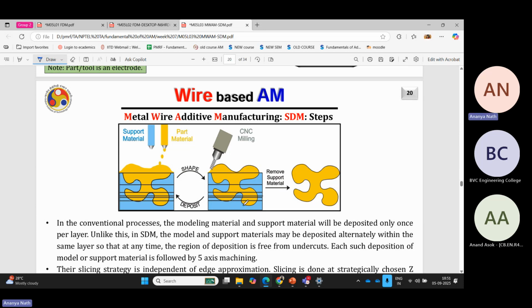So this is the shape manufacturing process where you divide your part into a few shapes. From here, the actual part is starting. So this is one shape. This will get deposited first, and then you will move up. Then this portion is almost the same, so this portion will get printed.